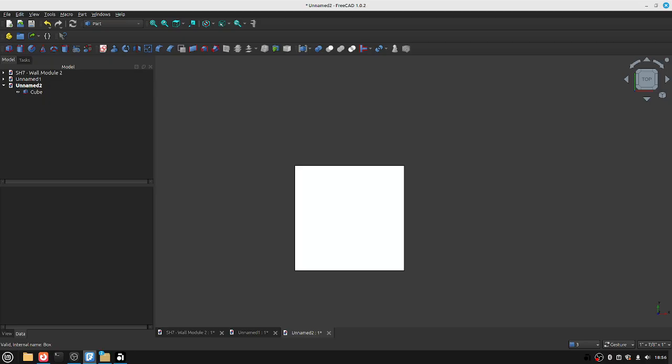Also, are you familiar with downgrade in the Draft workbench? I haven't used it. No. So what I was doing was taking the wall modules individually, because you guys already have them, using downgrade, and then that breaks it into the individual lumber pieces. So that was helpful for generating a cut list. Yeah. That was really helpful. Okay. Downgrade within which workbench? Draft. It's just an arrow. It's a blue arrow pointing down. Okay. So that was really helpful for me.